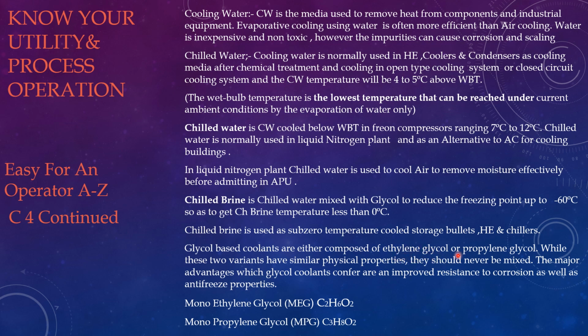60% water and 40% glycol is used to reduce the freezing temperature of the chilled brine. Monoethylene glycol, MEG, is C2H6O2. Monopropylene glycol, MPG, is C3H8O2. This coolant, or glycol, or chilled brine is used nowadays in the latest technology LNG regasification.